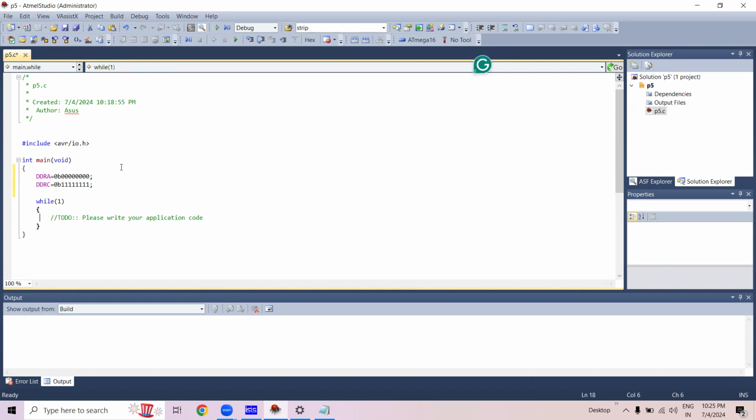So here we have to compare that if the button is on, the LED must be on. If is here. So how to write the if syntax in this AVR coding? Simply write if and then write your condition, whatever it is. After that, start the curly bracket, write your statement inside, terminate the line and close the braces. So this is the whole structure for the if condition.